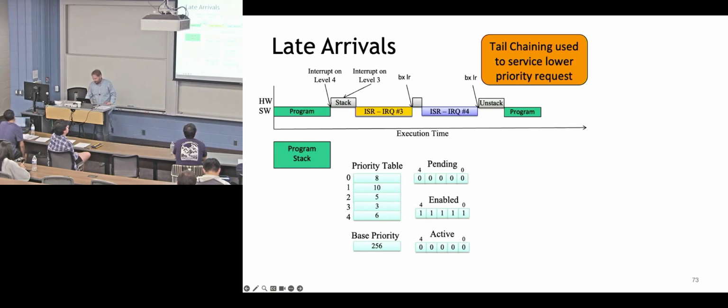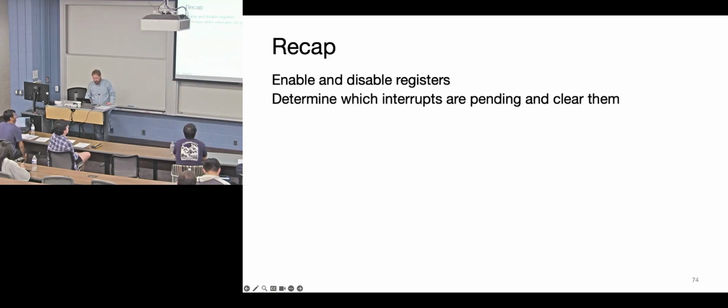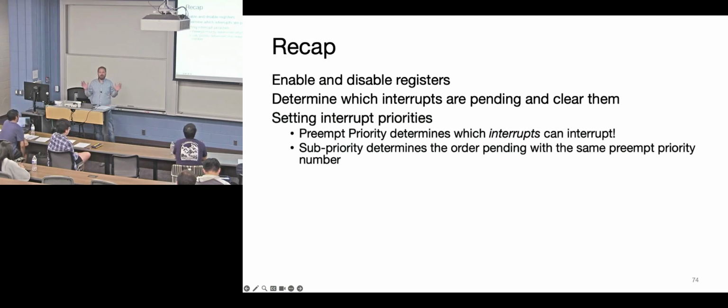All right. So we can recap here. There's a bunch of new registers to understand how they work. We highlighted a bunch of those in green, so you can enable or disable interrupts. You have separate registers for that. If you want to clear a pending interrupt, you have separate registers for that. A minor detail to keep track of when you're frustrated in lab and you're like, I'm putting bits in here, nothing's happening: remember that there's two addresses.